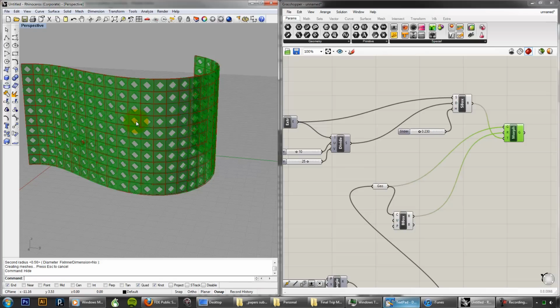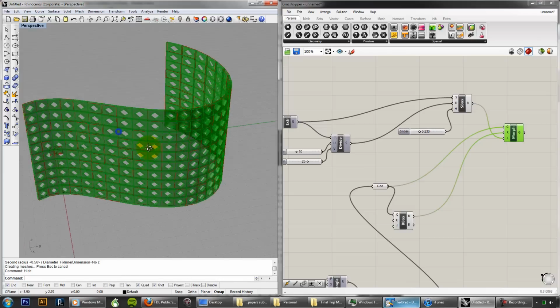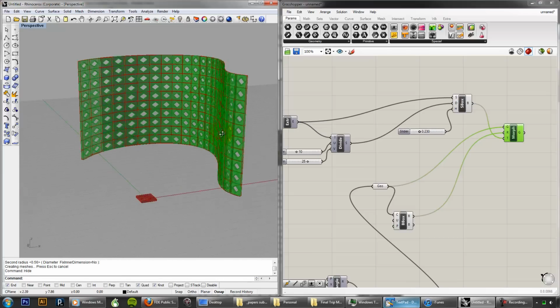The morph box is kind of a last-ditch thing. It always works, but it's not as powerful, and it's not as clean and as fast as building it yourself from points and lines and planes. But for some of your projects, nothing else is going to work. So I do want you to understand how this works. It's great for prototyping. Looks great.